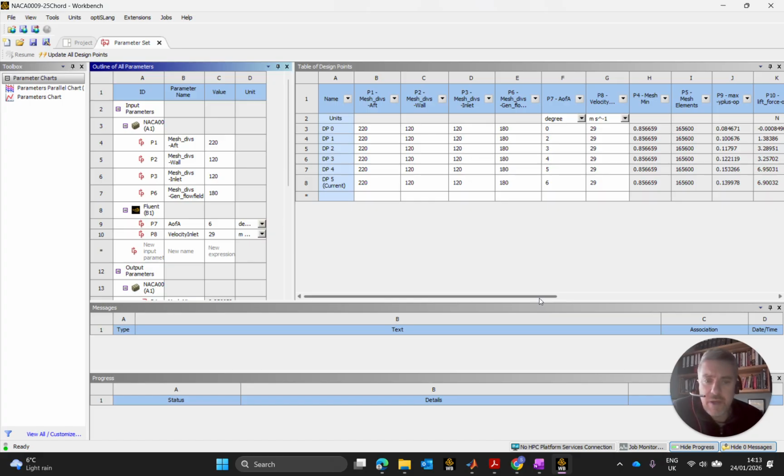What we did find was that it's more than likely because we're running a steady analysis as opposed to a transient analysis. And that makes perfect sense when you think about it, because we've spoken about it so many times in this series that at a Reynolds number of 50,000, there are transitional points and locations of transition where the laminar flow develops into a turbulent flow.